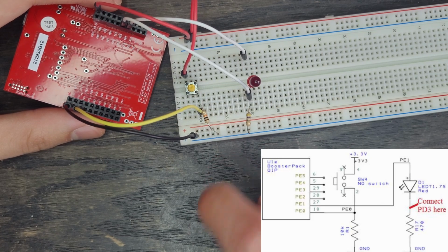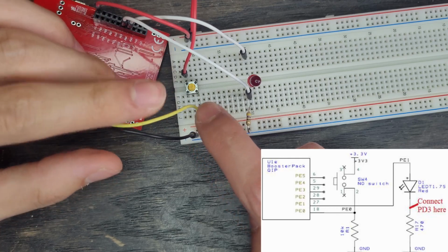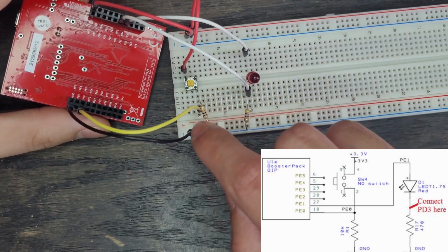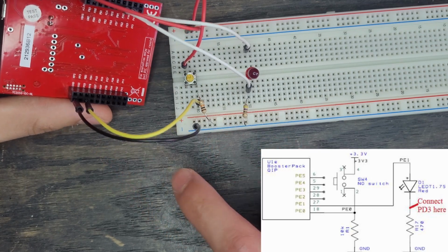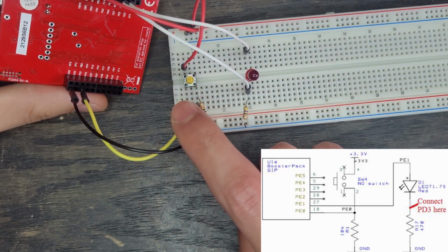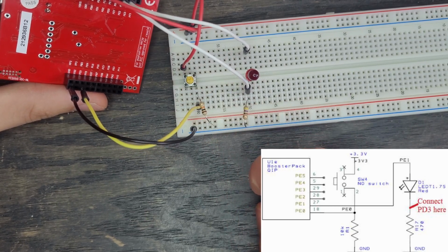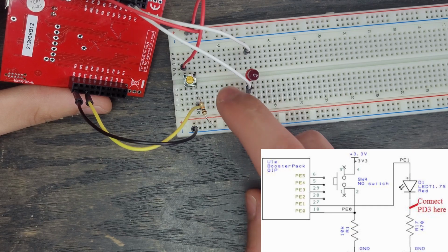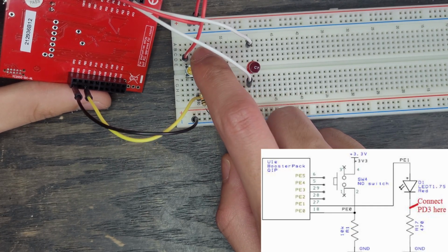Well, we know that one side is going to be connected to PE0, which is in parallel with our ground. So our ground's right here. That way we plug in this yellow wire to our PE0. It's going to be right here, third on the left-hand side of our board. So that is going to plug right there at this node. We are going to have our switch. It's going to plug into number 2, which is this one. And then we can have number 4 up here.